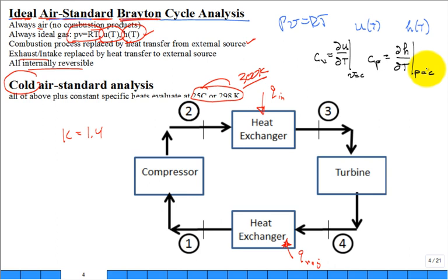Perfect. But now somebody says, I want to use this very general equation for only an ideal gas. H, this is the key observation, is only a function of T. So mathematically, do I need to use this type of derivative, or can I replace it by this type of derivative? I can replace it with the ordinary derivative. I don't need the partial derivative. So for an ideal gas, this becomes the ordinary derivative of the enthalpy with respect to temperature. Is it restricted to pressure constant only? Nope, you just lost that restriction.